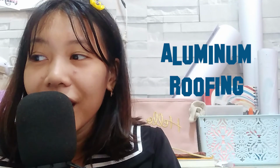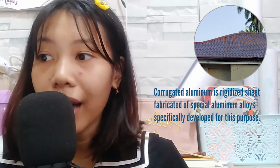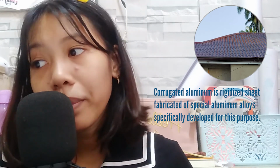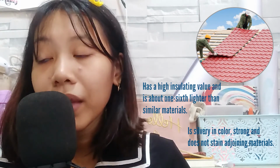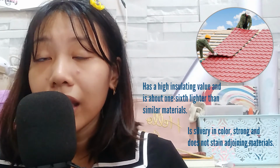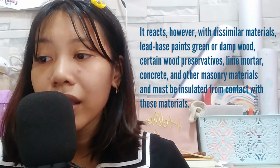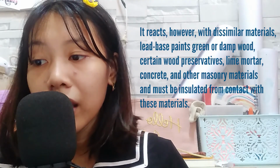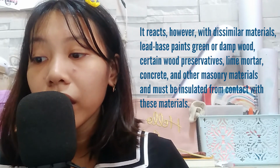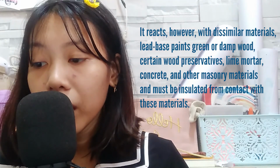So let's proceed to the aluminum roofing. The corrugated aluminum is rigidized sheet fabricated with special aluminum alloy, specifically developed for its purpose. It has high insulating value. It is about 1/6 lighter than similar materials. It is strong, has a silvery color, and it does not stain adjoining materials. However, it reacts with similar materials, lead-based stains, some wood preservatives, lime mortar, concrete, and other masonry materials, and must be insulated from contact with these materials.